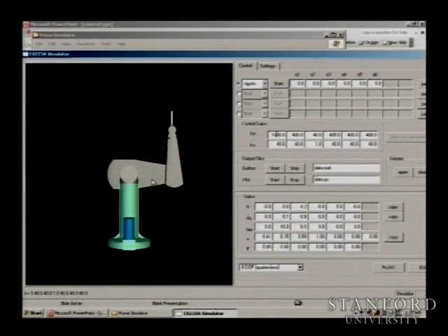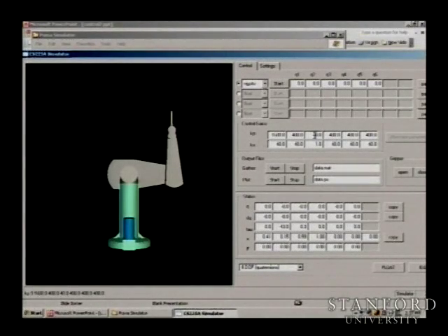So, in order to avoid that disturbance coming from the dynamics, what should we do with Kp? Make it smaller or bigger? You're not sure? Should we try it? So let's make it bigger. How big? 400? Okay, 400. Now you realize with 400, this is not damped enough, so we need to make this a little bigger. So let's make it 20.